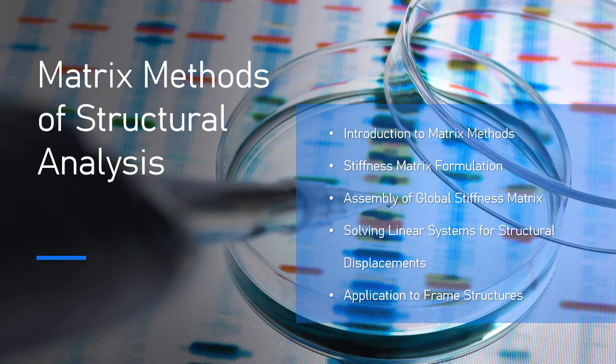After performing LU decomposition on the stiffness matrix, the system of equations Ku equals F is solved in two steps. 1. Solve Ly equals F for the intermediate vector y. 2. Solve Uu equals y for the displacement vector u. LU decomposition is particularly useful for large, sparse systems and can be more efficient than Gaussian elimination for these types of problems. 3. Matrix inversion.